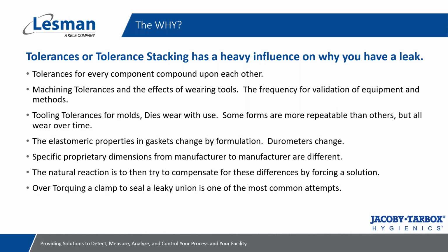You've got the elastomeric properties of the gaskets changing just based on the formulation, right? So if I'm using an EPDM versus a Viton versus a solid Teflon, all of those durometers of those materials change, that can allow some tolerance creep as to the overall thickness of the gaskets when it's compressed.